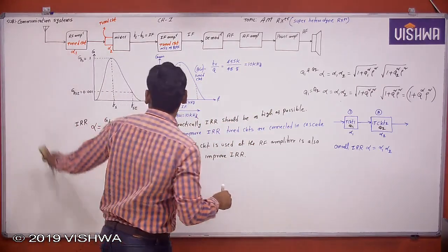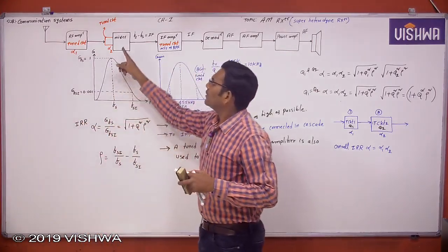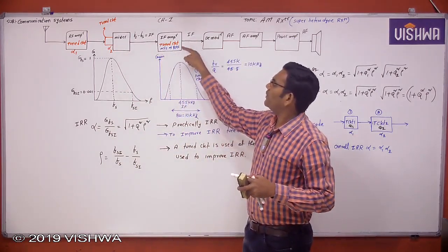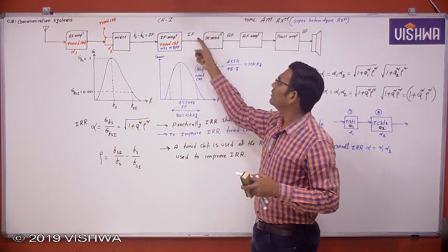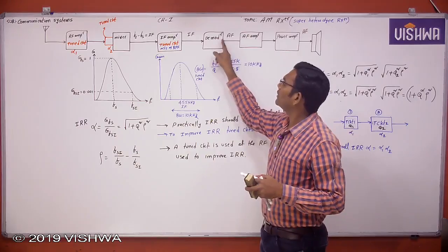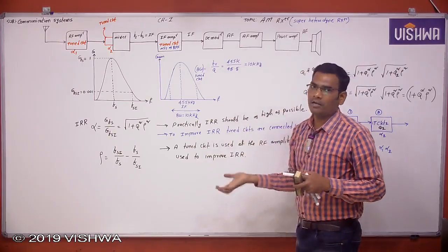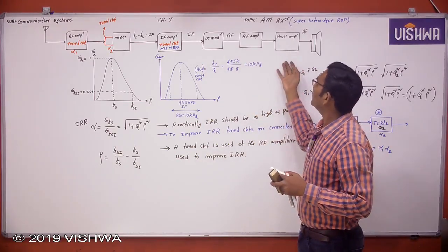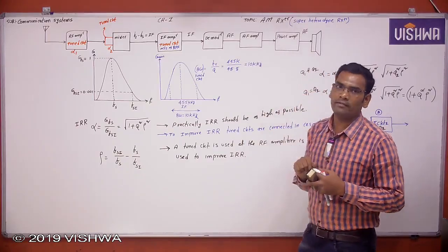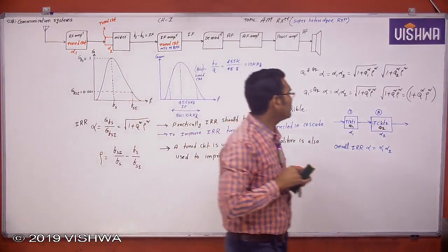Okay. Now this is the total super heterodyne receiver. Now this is the IF stage, then the IF amplifier increases the IF signal strength. Demodulator is IF to AF. The demodulator will get back the AF from the IF. The AF amplifier increases the audio signal strength. Power amplifier is for impedance matching. Both also try to improve the signal strength, and you can get a good quality audio signal. Okay, this is the total super heterodyne receiver. Okay, note down.